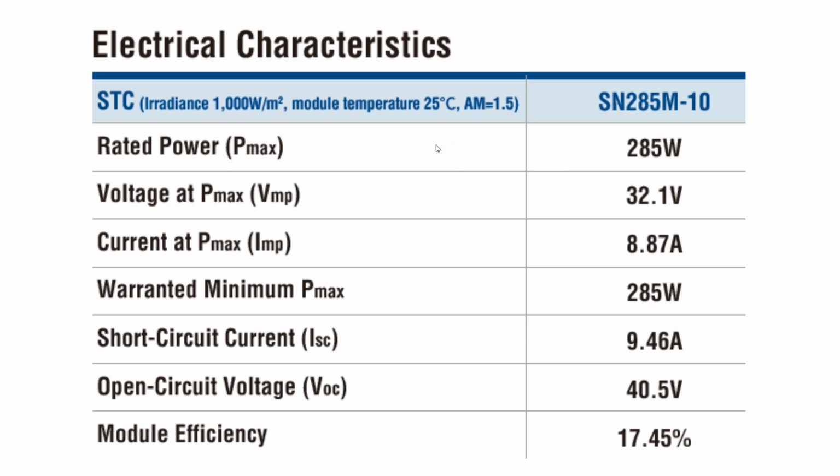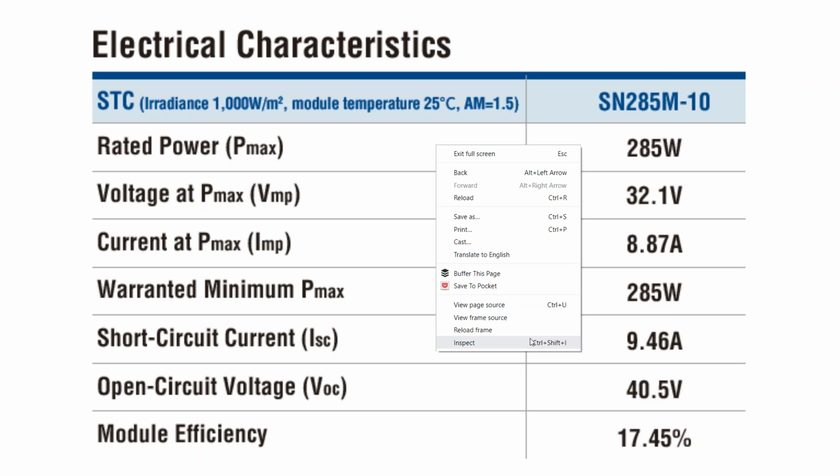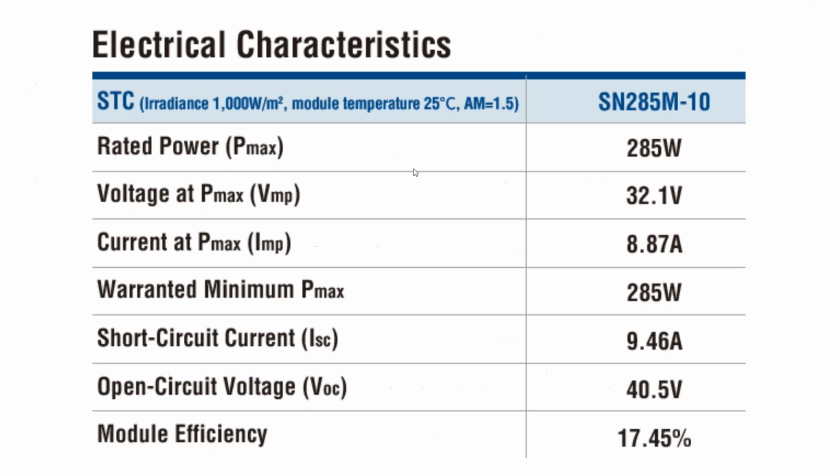Now, another thing that's kind of interesting about PVwatts as it relates to standard test condition. Now here's your standard test condition ratings, and we have it done at 1,000 watts per meter squared with a module temperature of 25 degrees C, and then this is called an air mass or atmosphere thickness. That's kind of the hardest one to nail down on what exactly that means, and it relates to how far through the atmosphere the photon is traveling.